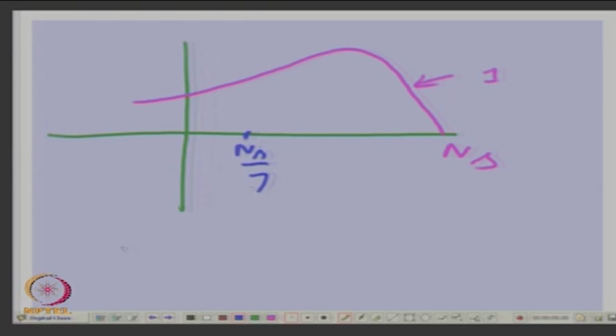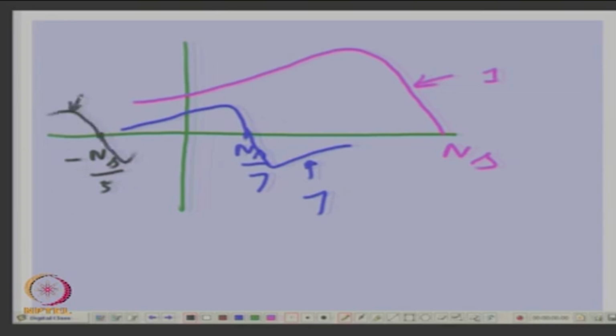So, it will give rise to a torque speed characteristic. How will that be? It will give rise to some torque speed characteristic like this, right. And there is another, say at 1/5 minus n, because this is the other direction, ns by 5 backward. So it will also give rise to its own 5th harmonic backward torque speed characteristic.